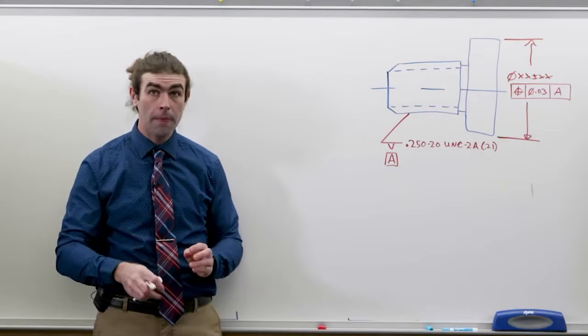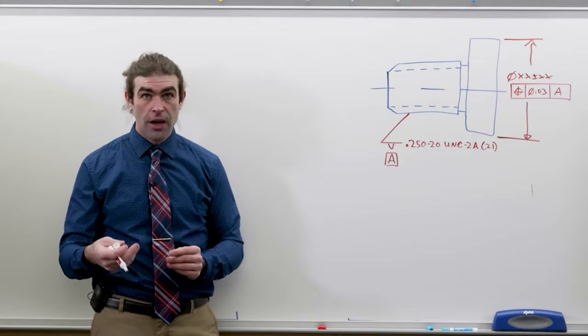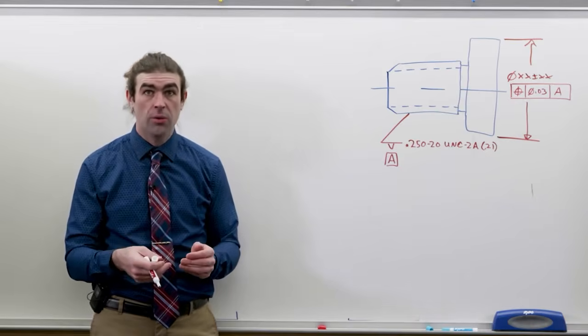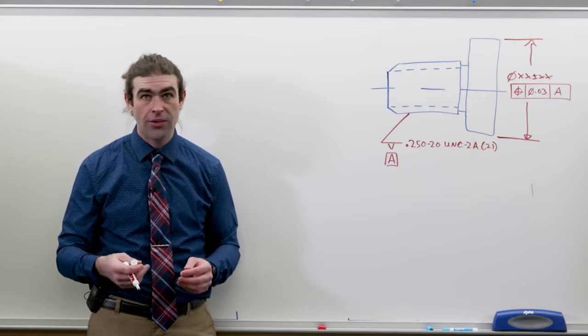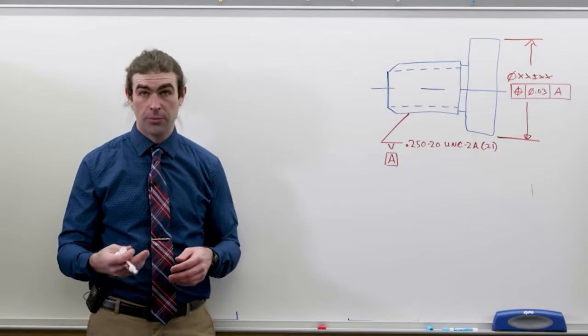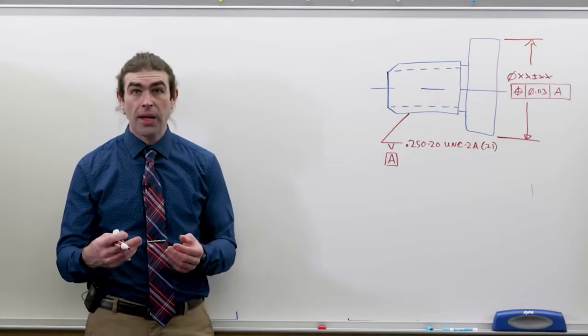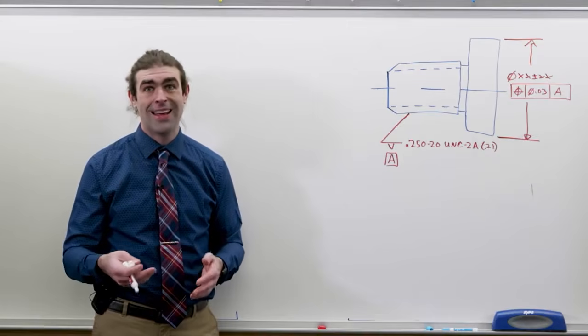Now, the tricky part is that when you go to inspect this, unless otherwise specified, the datum is the pitch cylinder, which is an imaginary thing in between the top and the bottoms of the threads. This requires expensive inspection equipment to capture, depending on the thread size, but it is the most functional because that is what's going to locate the thread at assembly.